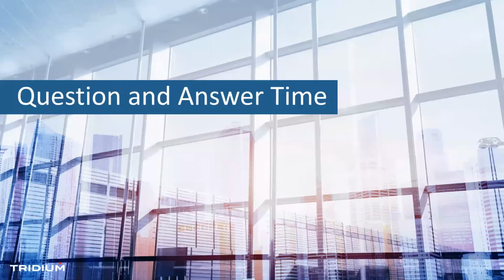Do the specification documents cover trending requirements or control sequencing, such as Guideline 36? Great question, and I should have probably mentioned that deeper. Sequence of operation is one of the most important things you can do in a good spec. So yes, the sequences are always going to be part of the spec. You might put in your specification, you shall use ASHRAE 36. I still think you should publish the actual wording there.